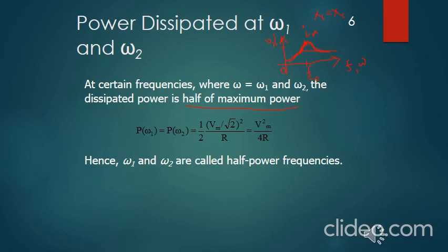After that, we have to find out the RMS value, that means to find out the average power of the circuit. As we know, I RMS is equal to 1 by root 2 times I maximum. We are calculating with respect to current, but it can be voltage, or any kind of parameter related to amplitude. But I RMS is 1 by root 2 I maximum. Then the curve will go through like this.